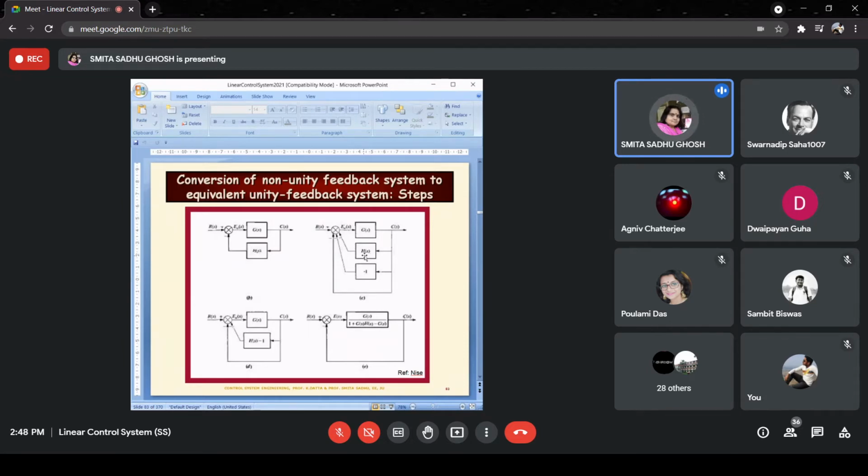Next, they have combined these two together. So H(s) minus 1 is what they have got, combining these internal ones, the ones in the middle, so-called. Combining these two together, they've got this, and then they've combined this one and that one. So again, over here, G(s) by 1 plus G(s)H(s) would be the feedback path transformation that you have to consider. Ultimately, after combining, they've left the negative unity feedback separately.